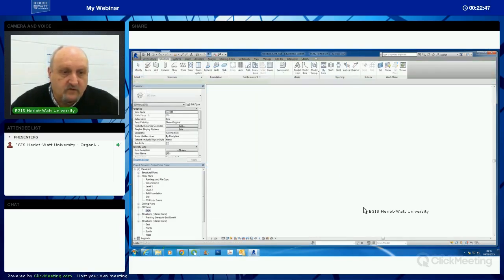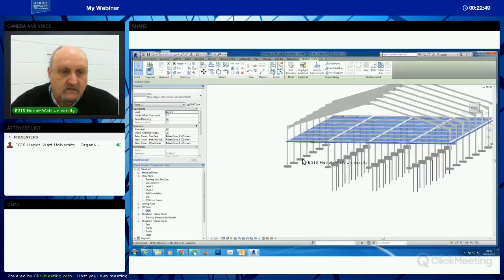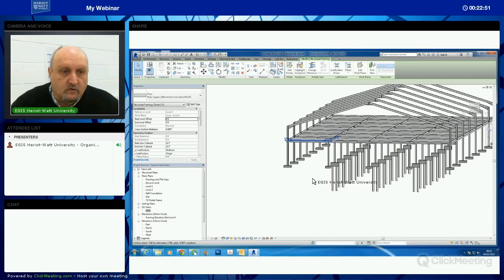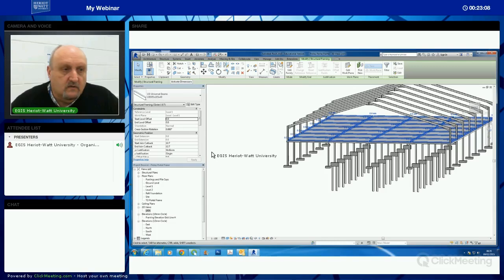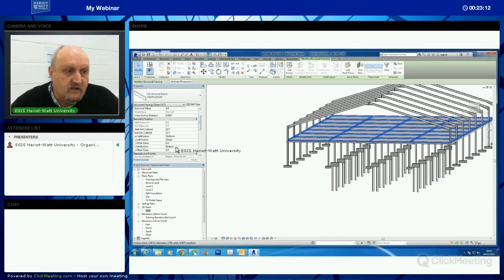Go back to 3D and we should see the problem. These beams still have this edge justification at bottom, so they're drawn along the bottom of the floor, and they haven't been given a negative value offset, so they'll sit under the floor, i.e. support the floor. I'm going to fix all that now. Select one of the beams, SA to select them all, and firstly I'll change the Z justification here from bottom to top. You should see them pop down a wee bit.